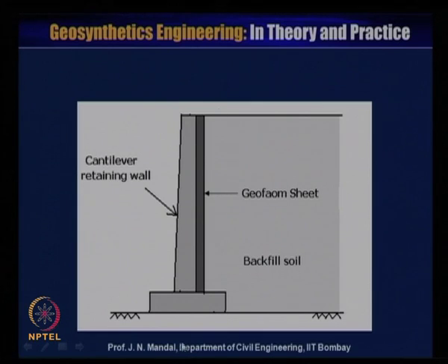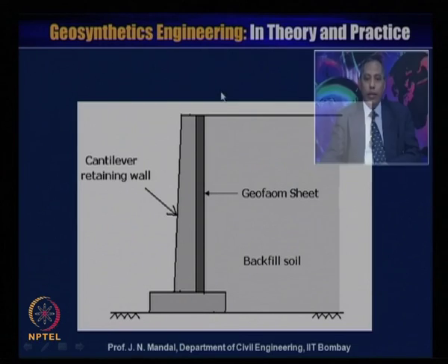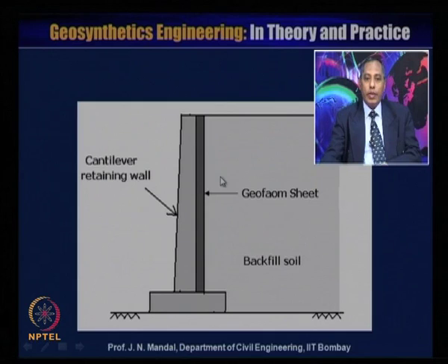So let us say this is the wall, a cantilever retaining wall, here is the geofoam and this is the backfill material. We will change the thickness of the geofoam material and observe how the lateral pressure either increases or decreases by the inclusion of different thicknesses of the geofoam material.